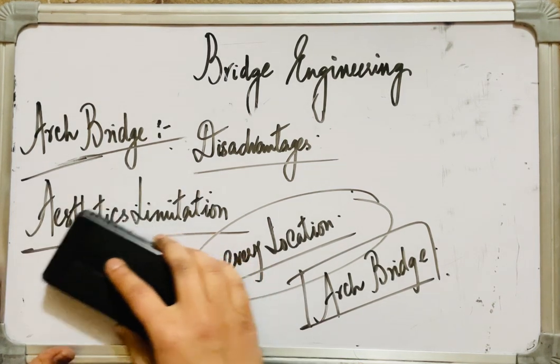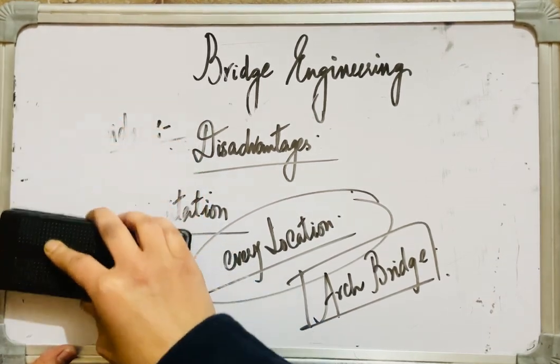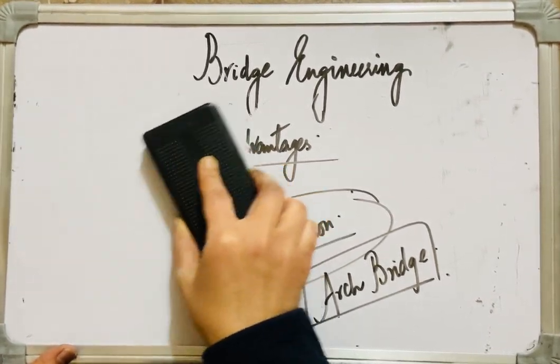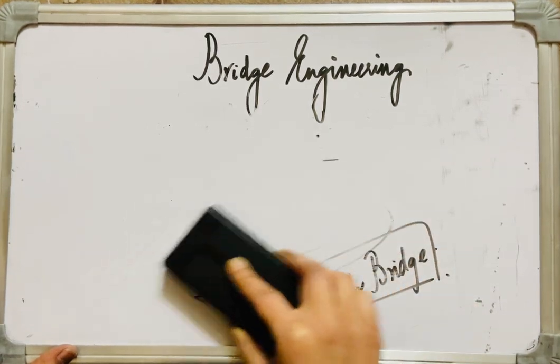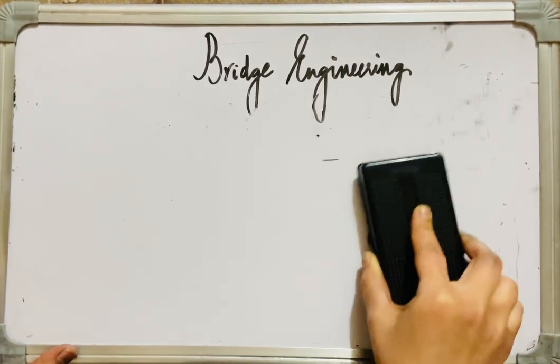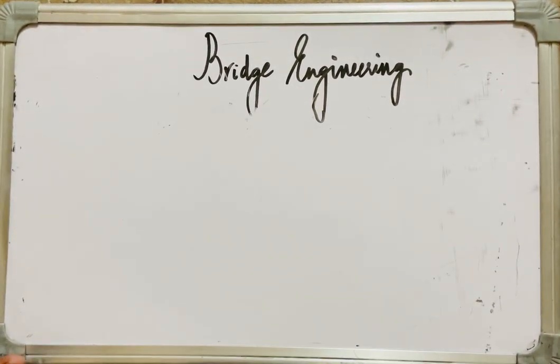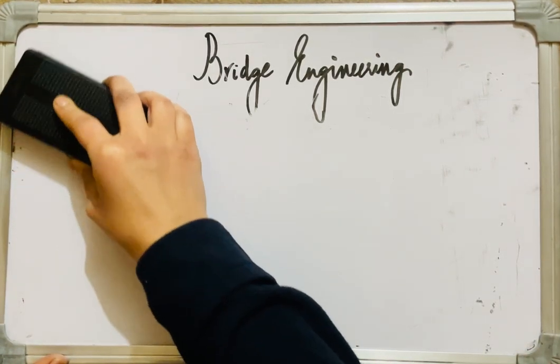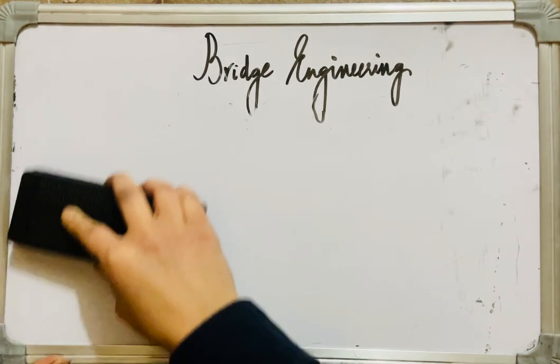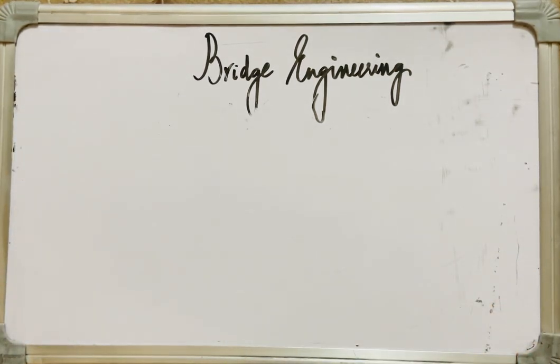All right, so we have studied 3 bridge types today. We have the 7 basic forms of the bridges. We studied 3 today: the beam bridges or the girder bridges, wherein the bridge deck is supported by means of the cross beams or the girders and the loads are carried by flexure or bending. Then we studied about the truss bridges, wherein the bridge deck is supported by steel trusses, which are interconnected triangular units, and this geometry provides them exceptional strength and stability.